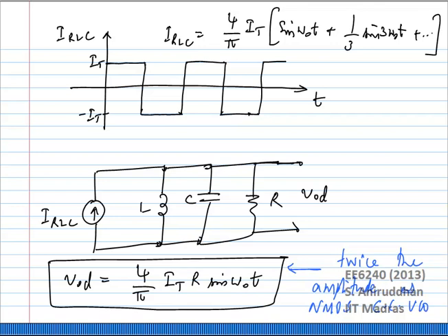Okay? So really, the amplitude of the VCO, or imperfections in the amplitude of the VCO, is of very little concern. What is more important is the phase of the VCO, the zero crossings, right? These are very critical for a number of reasons. Obviously, the mixer switches at exactly the zero crossing, right? You want the zero crossing to be fast, maybe for certain requirements in the mixer, okay? So instead of a sine wave, you may want a square wave and so on. But really, whether you look at a sine wave or a square wave, you are talking about preserving exact zero crossings. Okay, that is the number one thing we are interested in from the VCO.